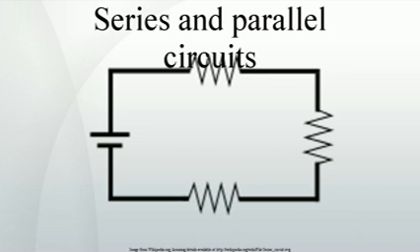A series circuit's main disadvantage or advantage, depending on its intended role in a product's overall design, is that because there is only one path in which its current can flow, opening or breaking a series circuit at any point causes the entire circuit to open, or stop operating. For example, if even one of the light bulbs in an older style string of Christmas tree lights burns out or is removed, the entire string becomes inoperable until the bulb is replaced.